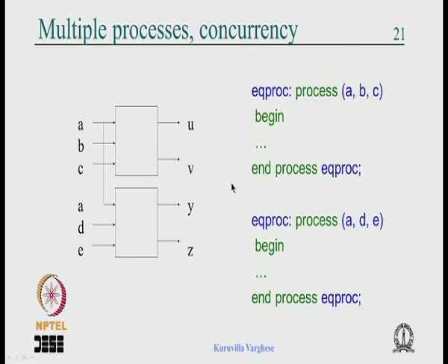So when you have, say, 3 concurrent statements and 5 processes, and something happens, everything is concurrent, like you have the same signals appearing in the statements as well as in the sensitivity lists of the processes. When the simulator handles the simulation, everything needs to be computed at the same simulation time. Something changes, it's not like a sequential language, the whole computation has to be done. So that is how the concurrency is handled by the simulator.